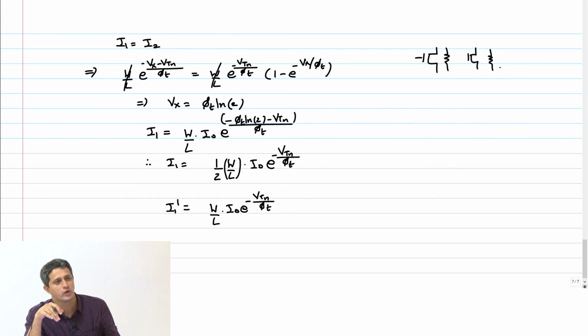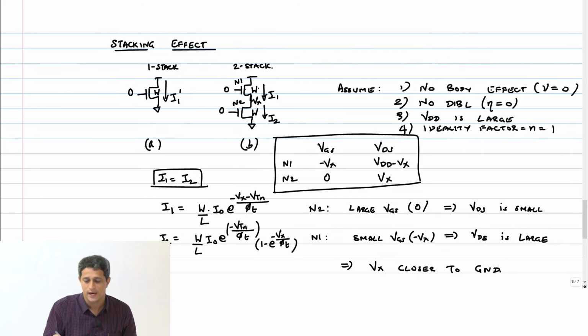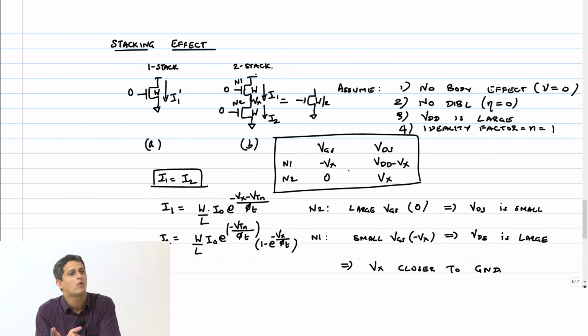So what I wanted to show you here is, if I don't consider all these short channel effects, leakage current is not going to come down drastically, because now instead of this, I will simply use a transistor like this. Even when you consider delay and other things, it's going to result in a transistor with W by 2. This is equivalent completely with respect to delay and everything. So why will I go and add the extra transistor, make it more area, and then get the same leakage current?